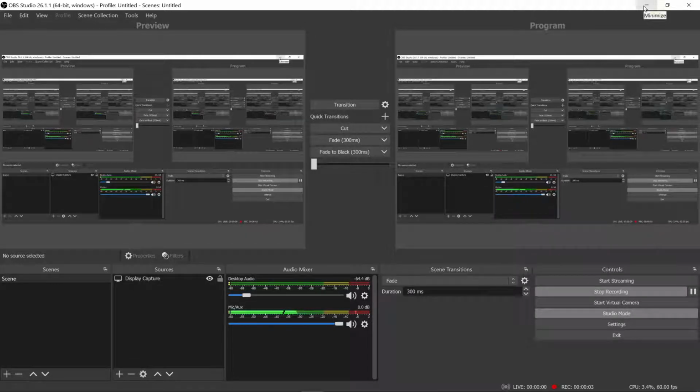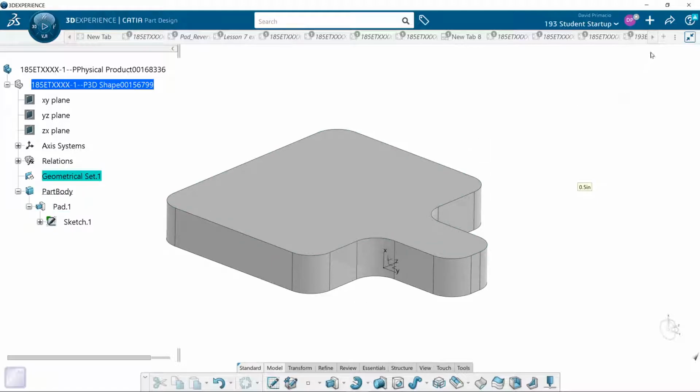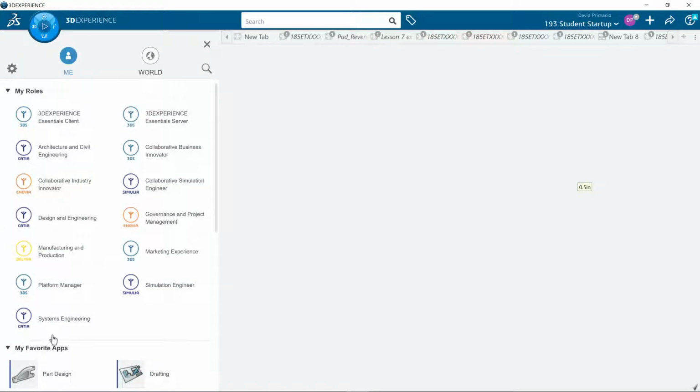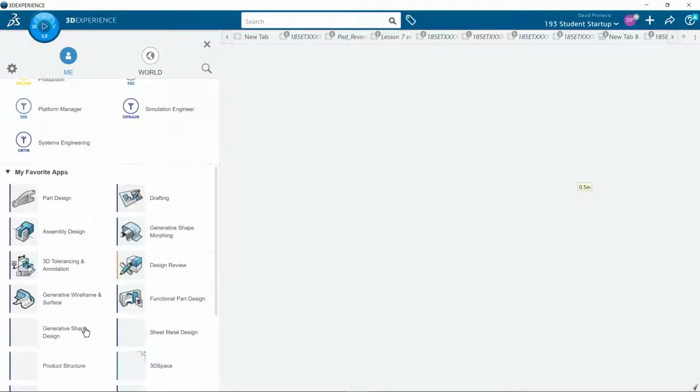Are the negative values because of the rotation of the tool? Like on a router, you can only route one way because of the way the bit spins. Is that what we're saying? When you get into the 109 class, you'll talk more about climb cuts and conventional cuts. But if I'm doing a climb cut, whatever direction you're climb cutting, as it wraps around the part, is going to be positive or negative values, depending on what direction you're machining.